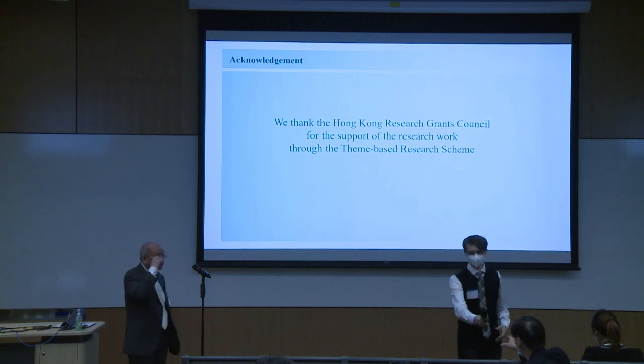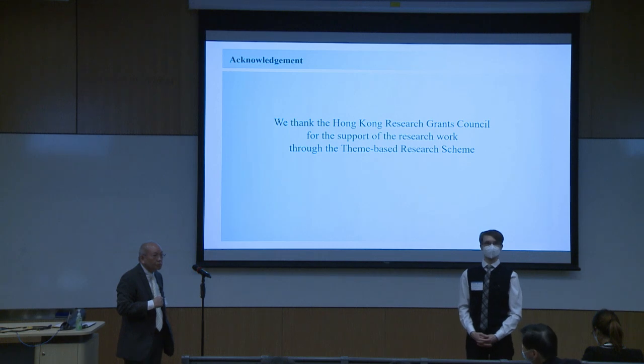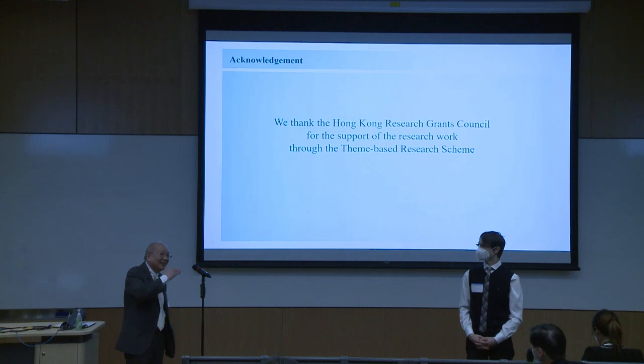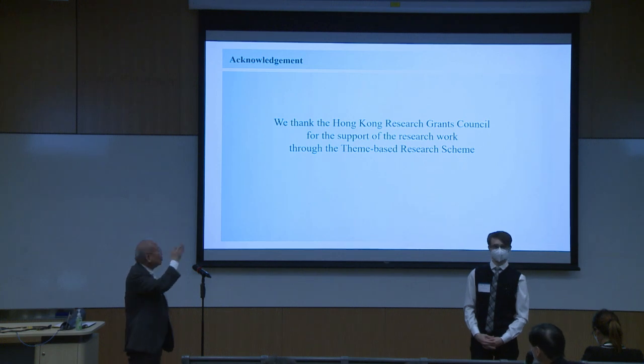Another question I'd like to ask is you said your scanning range is -40 to 40. What limits you? Because it looks like you can scan -90 to 90. Well, typically for the antenna guy, the scanning from the main beam, if it is less than 5 dB, we stop there. Although you can see that, yes, we can go further. Because the power is high, in fact, we can scan higher.